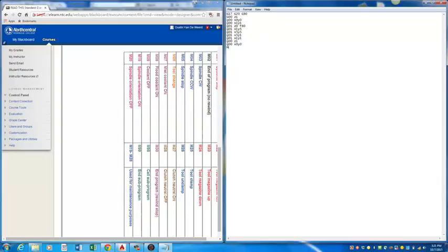So if I put that in here, what that does is it says this is the end of my program and I want you to rewind to run another part. So this M30 command will give you a continuous run, sort of. It'll ask you to push start every time, but it'll loop around, push start, run it, loop around, push start, run it. So a continuous process, like you're running out multiple parts.